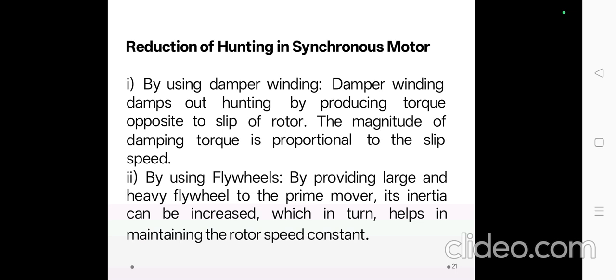But if the power factor is maintained high, the current drawn from the supply is less. The high current due to the low power factor has the following disadvantages. With higher current, the conductor size required is more, which increases the cost. The power factor is given by cos phi equal to active power by apparent power. Thus, for fixed active power P, the lower power factor demands large kVA rating alternators and transformers.